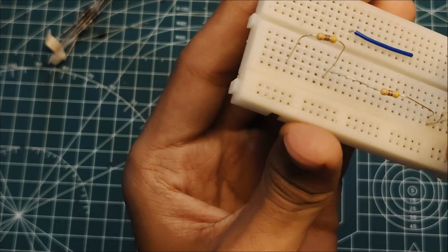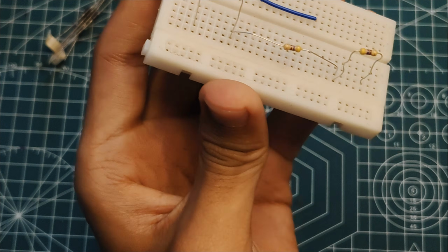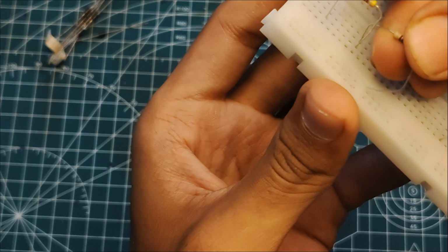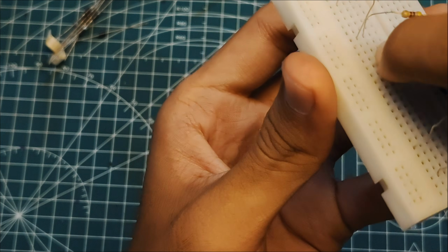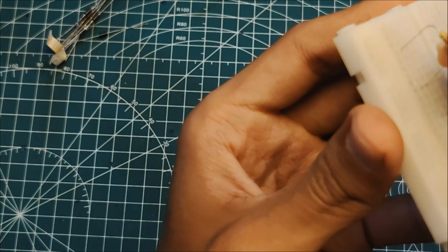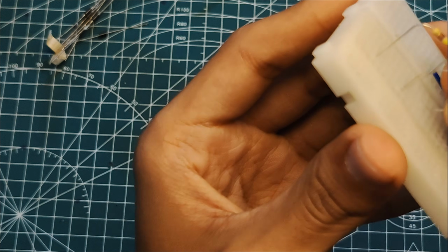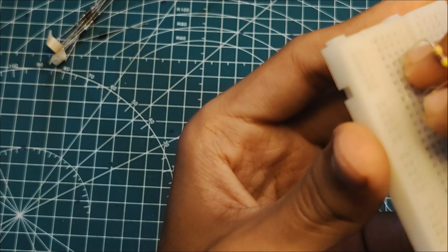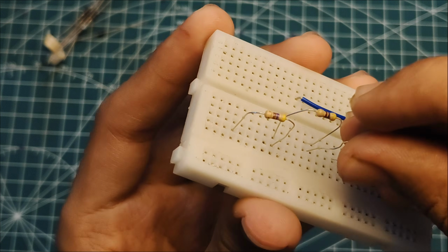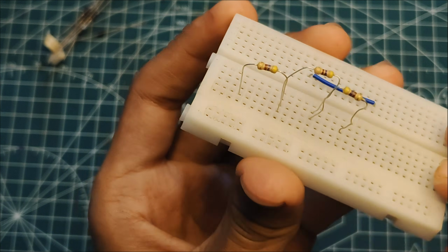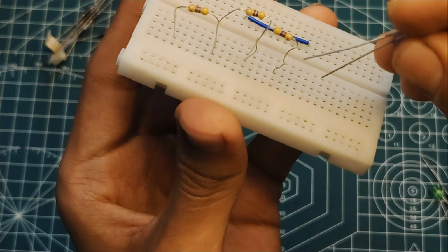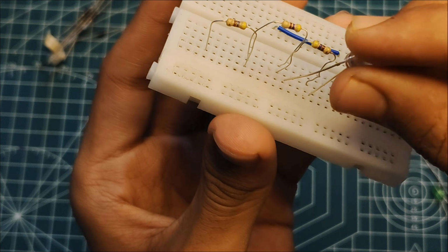So grab your breadboard. This time we have already built this voltage divider. Let that circuit be there, because it helps us a lot: we don't have exactly 3.3 volts or 2.5 volts to run these small LEDs, because going with a higher voltage would burn them up. So try to have this same circuit around that voltage divider, and grab any of your LEDs and connect it at the end of it.